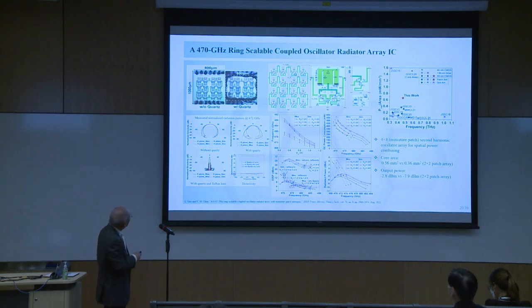And it is another IC that we have designed, making use of our specialties in antenna design. By making use of this particular antenna design, we can reduce the size of the antenna by 1/3, and we can actually improve the radiation efficiency from 31% to 69%. Now, because we can reduce the size of the antenna, we can reduce the overall size of the array, so that we can have the highest output power per chip area using this 65 nanometer technology.